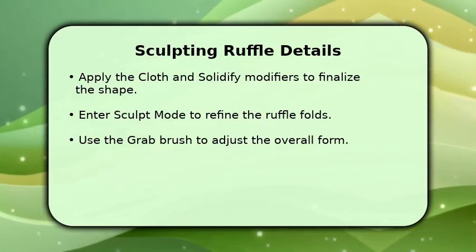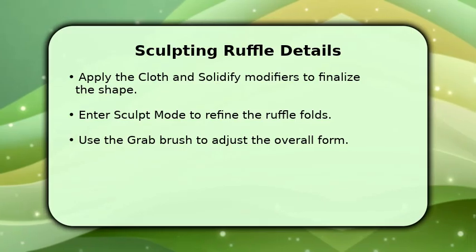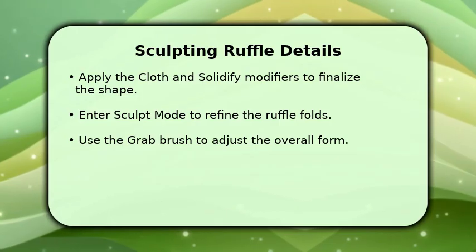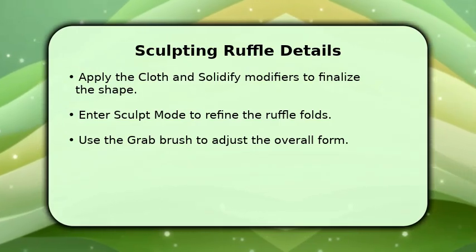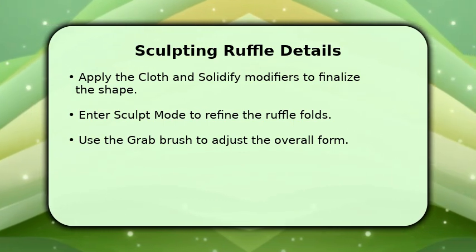The grab brush is excellent for gently pulling and pushing the fabric to create larger, flowing folds. For sharper, more defined creases and edges, use the crease brush. Remember to use a low strength and a small brush size for subtle, realistic adjustments.